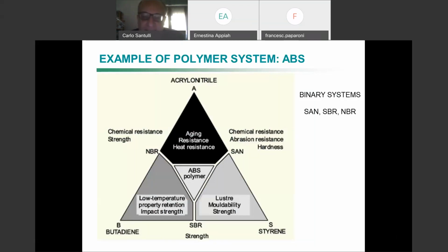And butadiene gives you a considerable impact strength. I'm going to talk a little bit about impact, as I also did in the last lecture. You can have heard about Charpy impact and Izod impact, but there is also falling weight impact. So basically, there is a ball that impacts on your plate, and you see when this ball penetrates.